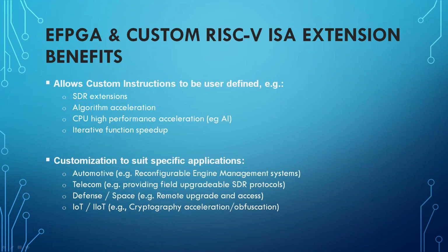The other advantage you get from an eFPGA is you can run these at wire speeds on the silicon. You don't have to come off the silicon, off the CPU on a PCB into another part and then do that process. You actually run this inside the silicon. So you're running this at wire speed inside the silicon.